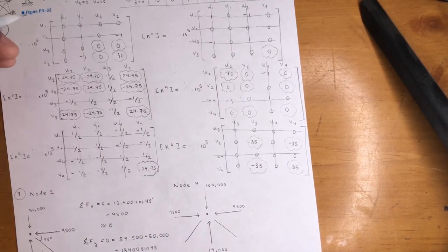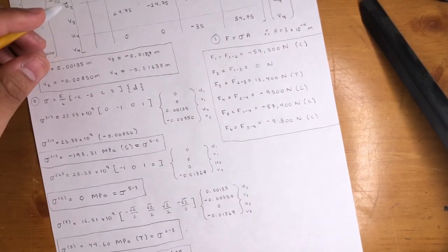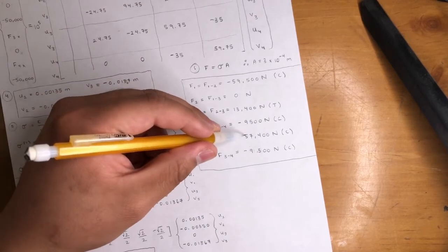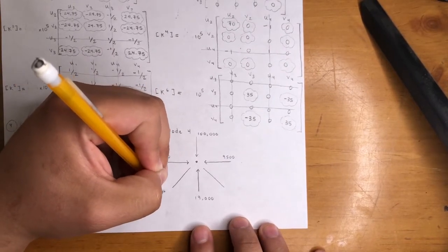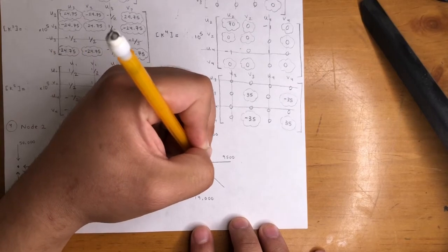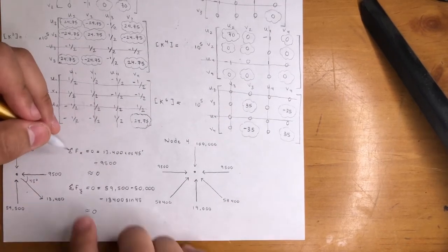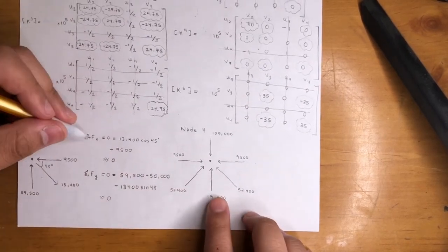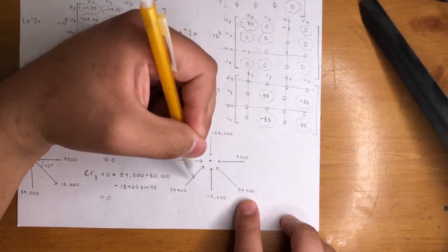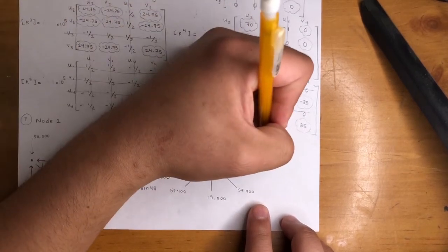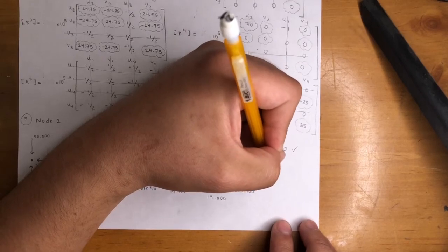Okay, so those two. Then finally, from 1 to 4 is the same as 5 to 4. So let's look at that, right? Remember, 5 to 4, this one right here, which is element 5, 1 to 4, negative 57,400. So it's positive 57,400, pointing into the node. Same thing here, 57,400. So now we got to do the summation just like we did here, right? Forces in the x and the y. But just by looking at the x, we don't need to, right? This 9,500 cancels with this one, and this negative 57,400 cancels with this one, the x components. So yeah, the sum of the forces in the x direction equals 0. Check.